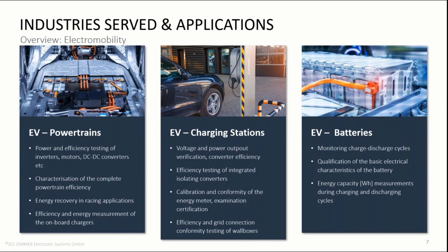These tests require the verification of the accuracy of the complete charging process by comparing the energy metered at each charging port with the energy measured by a reference instrument, that being a power analyzer. So both charging station manufacturers and certifying institutions can integrate power analyzers into their compliance test benches.